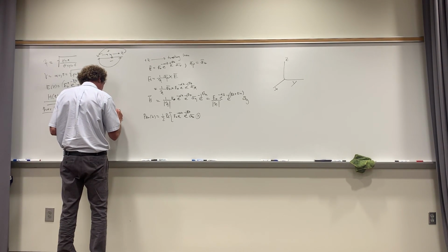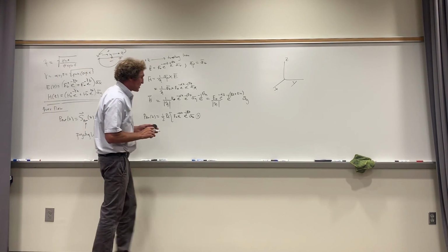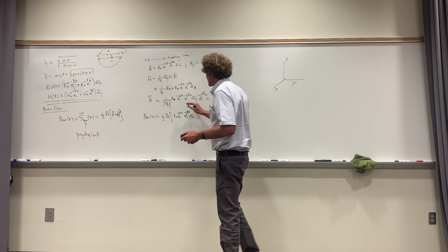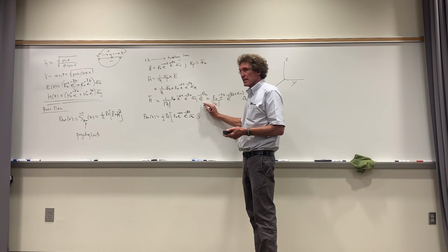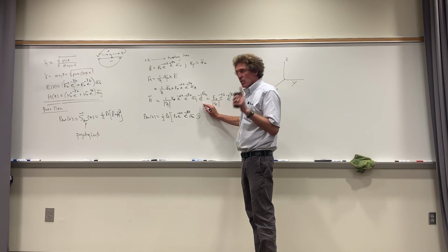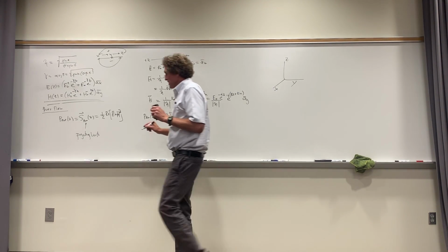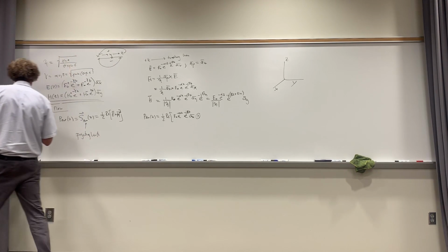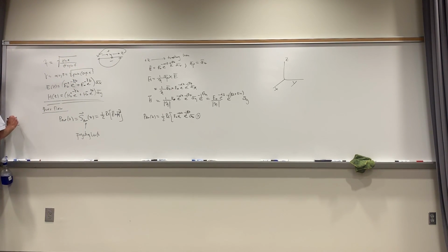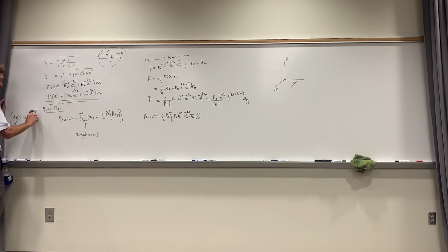And then I multiply by crossed into the H field conjugated. So if I conjugate the H field here, what happens? What does conjugation mean to you? It inverts what changes: the phase, the angle here, right? And look, if I have e to the minus j quantity beta z plus theta, right? Take that whole quantity, and if I conjugate it, the angle becomes opposite in terms of its polarity.